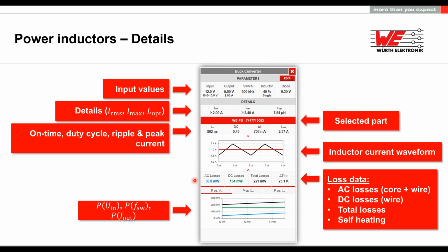And here the complete loss model is shown: the AC losses for this particular inductor, for the input parameters you have given. What is the AC loss, what is the DC loss, both put together as the total losses, and the temperature rise in the inductor for this application.